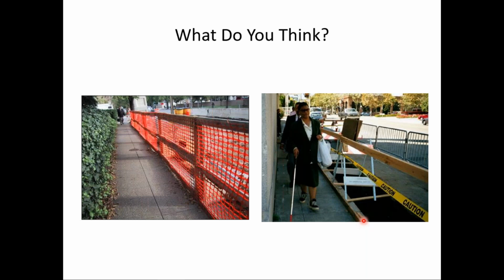But actually, generally, I have a bigger criticism. Let's imagine this is 6 inches high. Let's say it's 8 inches high. Let's say we have a board down here 8 inches high. So that would comply with PROWAG and the MUTCD. But what do you think about safety of this construction site? Notice there is a rail here. It looks pretty high actually, but there is a rail here. But notice all this open space. Somebody could get into that work area. In fact, it looks like this is an excavation here. A child could get in there and be seriously injured.